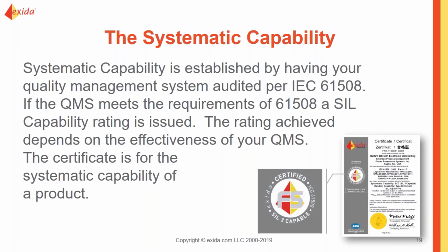We're going to look at how a company makes their modifications, if they use an impact analysis, how they notify their customers if there's a recall, how they get their information out, like the FMEDAs and the certificates and the safety manuals. We go through their process, their procedures, their documentation, all of that information. So, like I said, you have a bunch of rules and requirements, documents that are needed for a SIL 1.